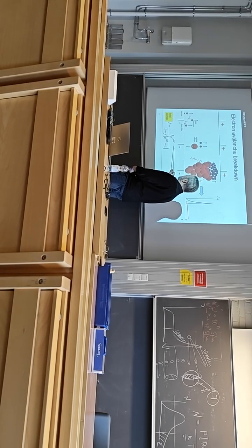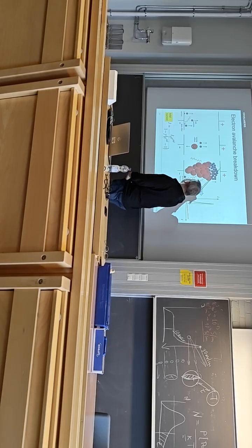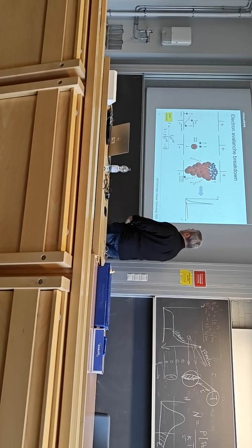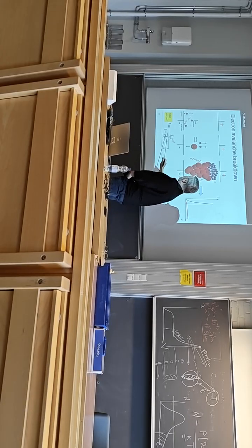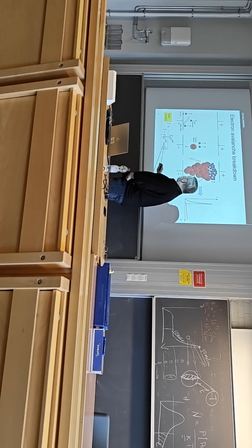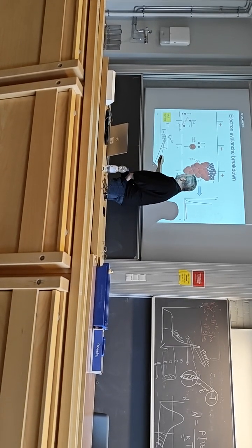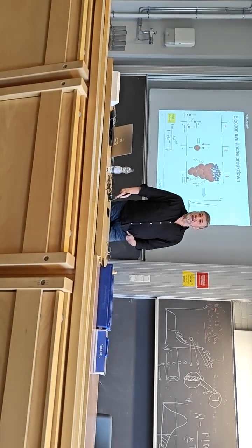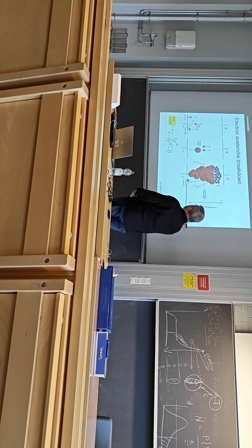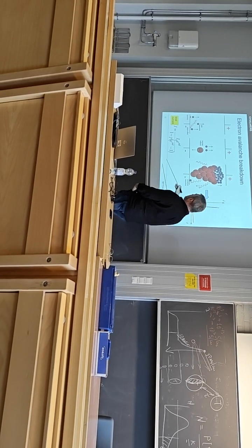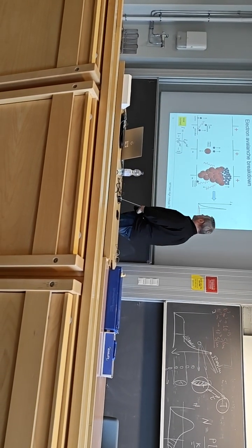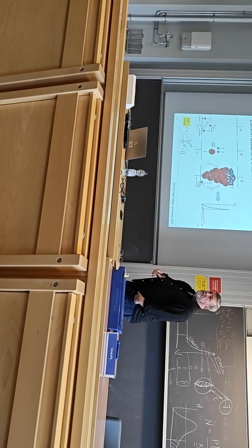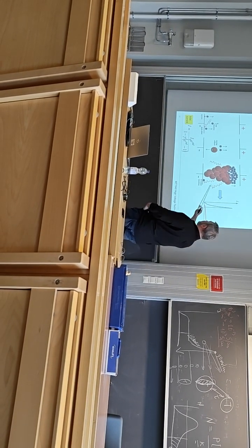So this exponent alpha d, d is the distance between electrodes. And then in the denominator we have this expression here. So basically this one describes the yield of secondary electrons from the cathode. Gamma is the coefficient which says how many electrons are released due to the impact of positive ions.